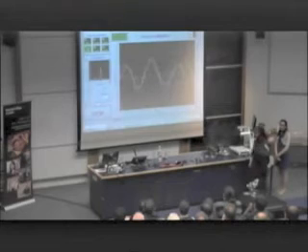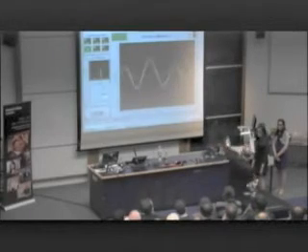But I think if I ask Amalia, my first assistant, to click 1800, it will go at 1,800 RPM. So I'm driving that motor. It's a pressure trace at 1, second trace at 2, third trace at 3. And what you see is the 3 traces along with time and pressure. White is near the engine, yellow is in the middle, and green is at the far end. So we'll start with the far end. The far end appears not to be sensing a great deal of pressure. Well, it wouldn't, because it's open to ambient.